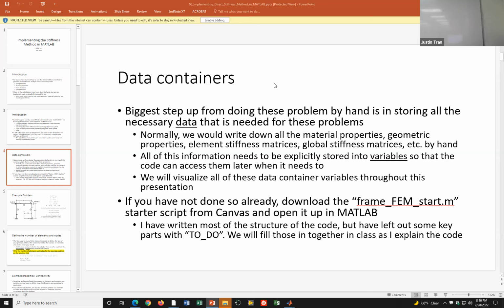Yeah. So it's true that each of these numbers can only displace along one direction. But these numbers are the global degrees of freedom for the structure. So X this way, Y this way. For this spring, I think it makes the most sense for it to displace roughly like this. And if you break down the displacement, it's going to go like this, but we could break up the vector like this. We solve them all within the same coordinate system.